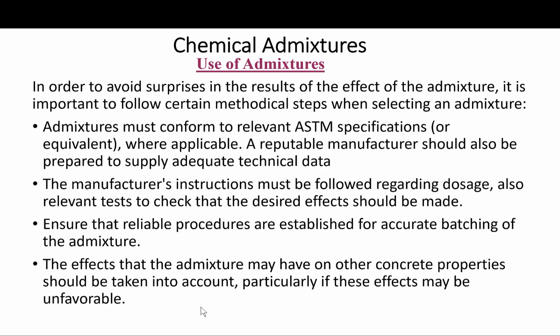And again, many stories about admixtures stored for an extended period of time, expiring after that. Of course, they cannot be used and should not be used, and that is basically throwing money away. Also, the preparation of admixture and procedures for introducing it into the concrete mix, when and how to add it.